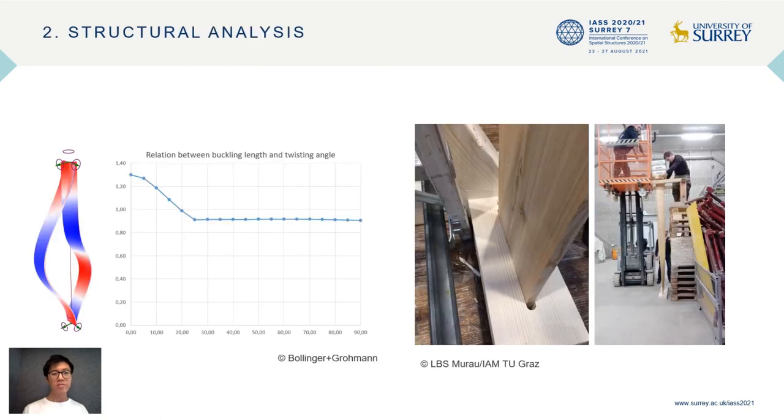The innovative construction principle in this research are the twisted wooden lamellas. These act as the structural elements for the vertical load takedown. By twisting the lamellas that are held between fully fixed supports, the buckling length can be reduced to up to 30% as compared to straight elements.